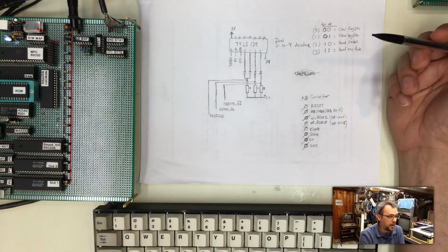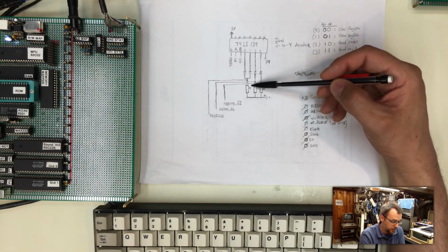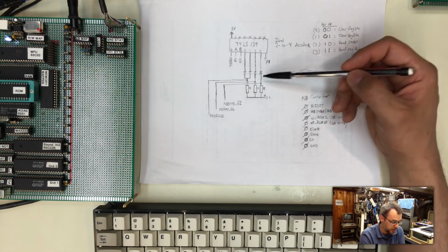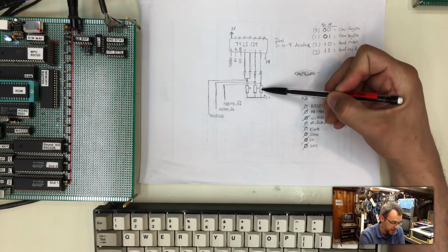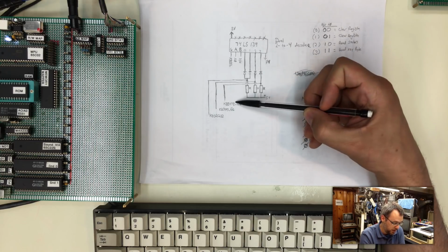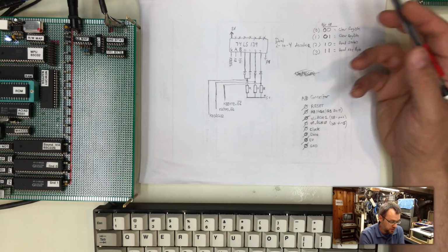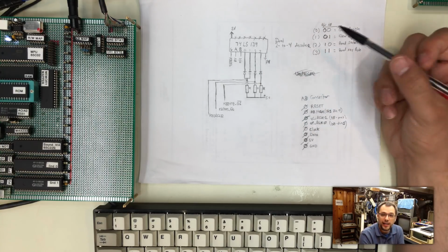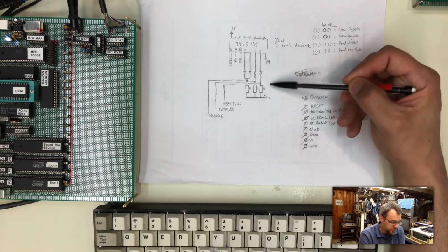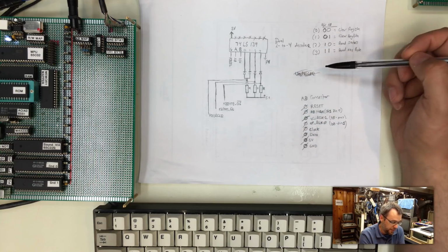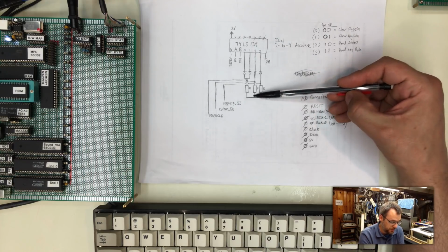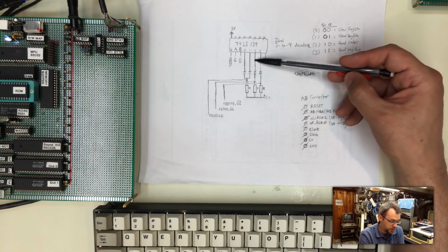Now, looking at this, I can probably make this even simpler. I probably only need my diode logic on these two, since we're combining those two. The diode logic probably is not literally required here, so on another iteration, I'll bet I can remove these diodes and these resistors, because these two wires can drive these two select lines directly, and I shouldn't need this pull-up stuff. But this is what I came up with to try to emulate basically a ROM encoder effectively. I think this is overkill for that design, but I left it in because that's what I came up with, and it functioned. So that's just a note that these diodes and resistors, at least on these two, probably are not required, because they're only driving a single line.